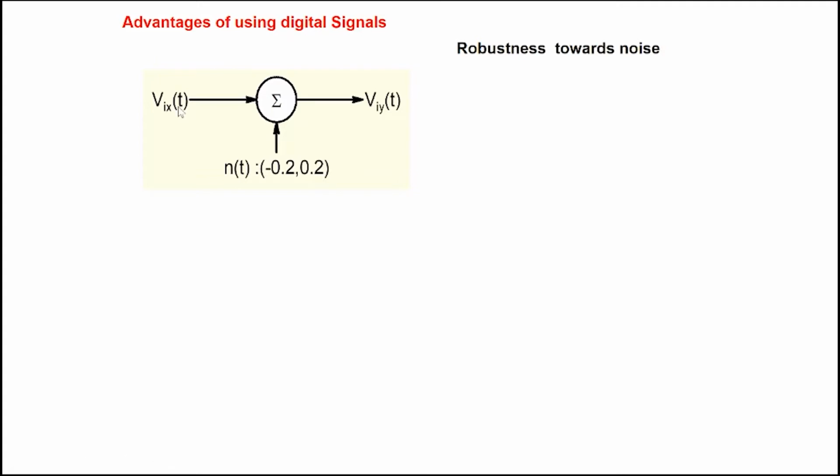We mentioned briefly that almost every electronic component, every resistor, every diode, every transistor, they're all sources of noise. And the power supply we have seen may have some ripple, and ripple is unwanted. So that's also a noise, an unwanted thing. And there are various environmental sources of noise. If you have imperfect switches, when you switch something on and off, those switches also radiate noise, and the noise can then get into your circuit. So there are various sources of noise.